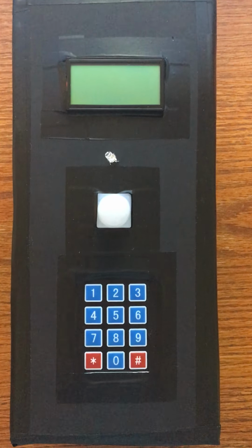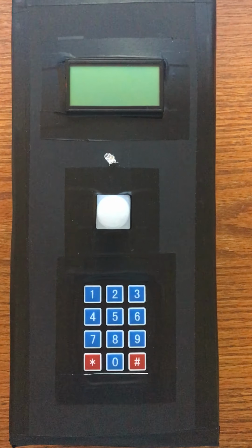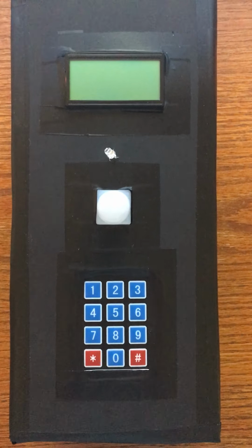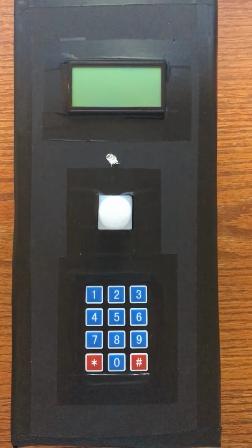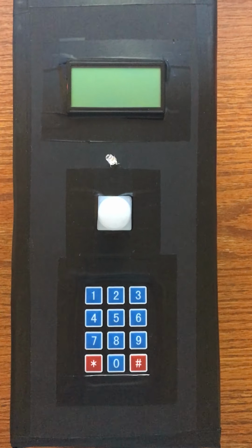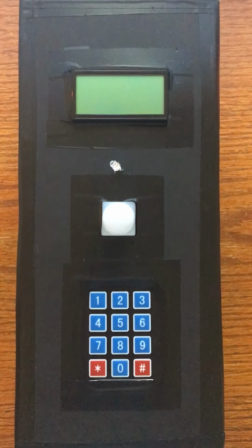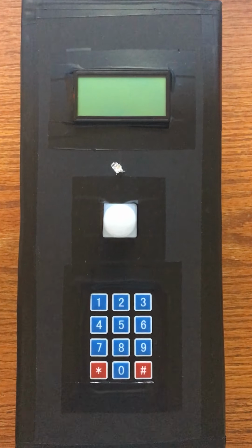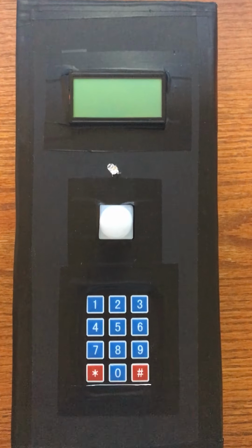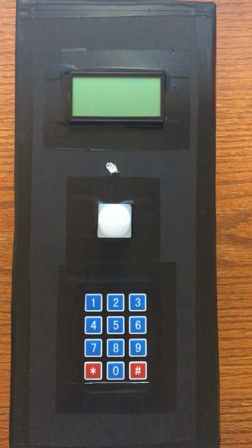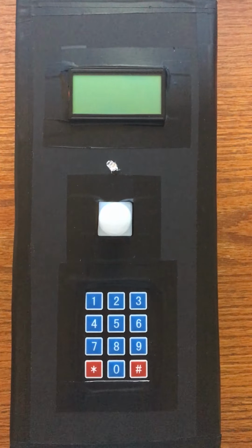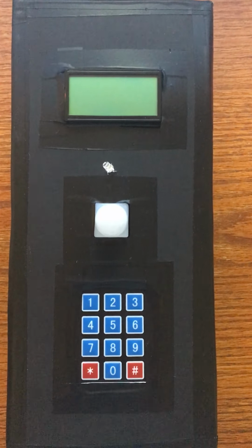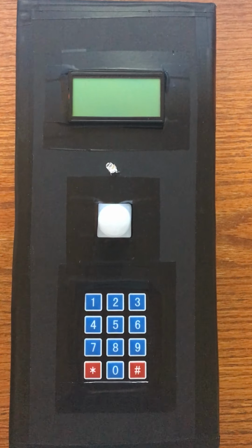The alarm system software architecture has 4 stages: countdown, alarm engaged, intruder detected, and alarm deactivated. Before the countdown stage, the software architecture sets the default alarm system PIN, which is 1, 2, 3, 4, initializes SPI, and configures the DAC to output a DC voltage of 1 volt, turning off the LED. During the countdown stage, the software architecture initializes the LCD, clears the display, and sets the cursor at the beginning of the first line. The software architecture then displays the message, alarm engaging in, and a countdown from 10 to 1, with a half-second pause between each number.